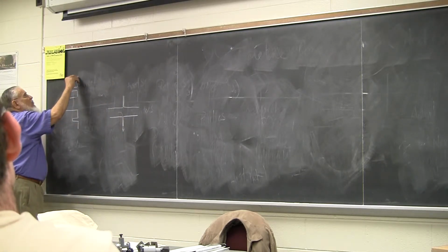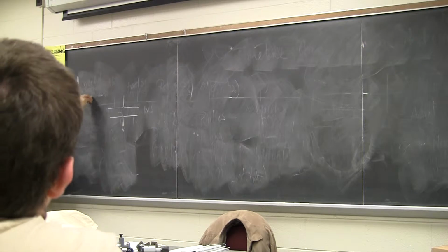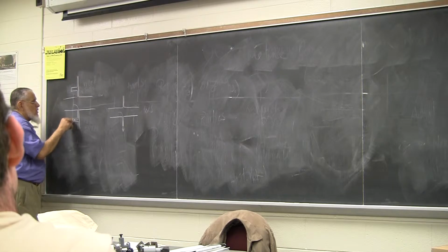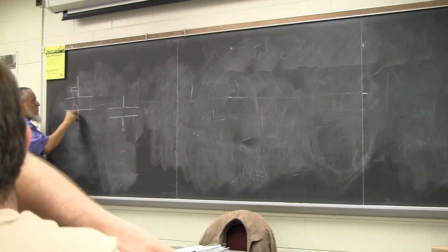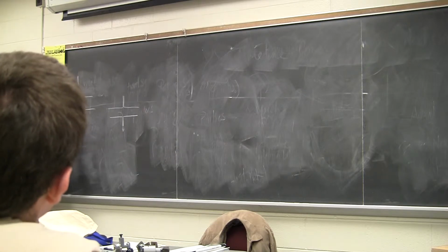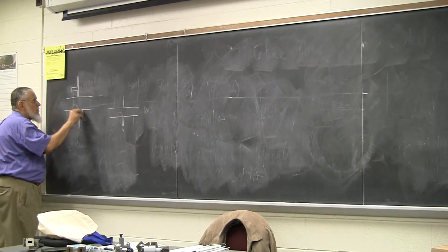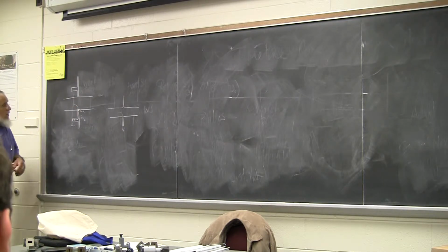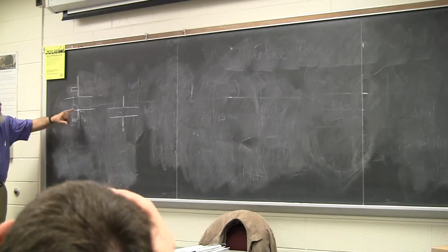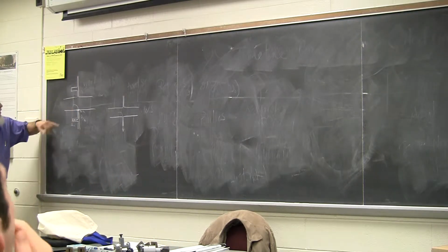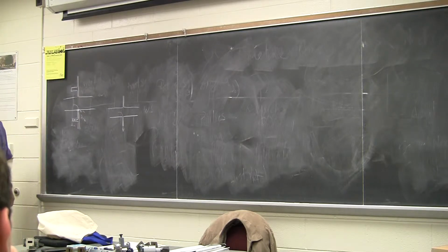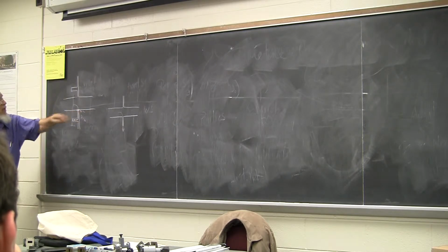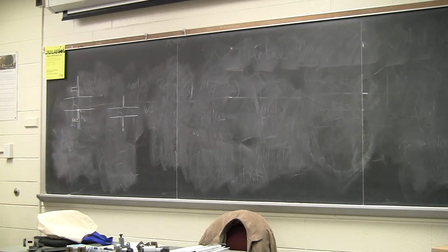Okay? Now, if you connect that to a flat one, let's say, the energy leaks from here, we'll see a short circuit here, and if the distance from here to there is lambda by 2, this short circuit reflects the short circuit here, right? We know that a short circuit lambda by 2 away will reflect a short circuit. So basically, you can get a better short performance across here than just relying on the contacts there, right?